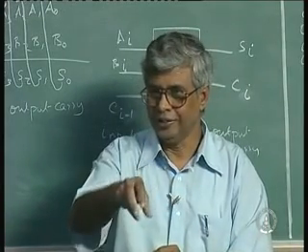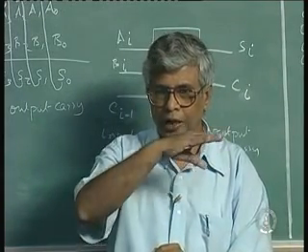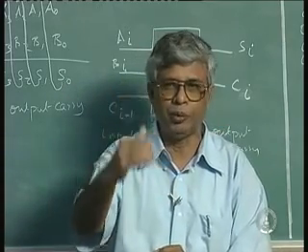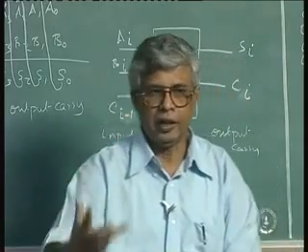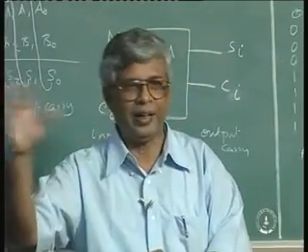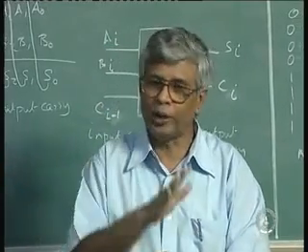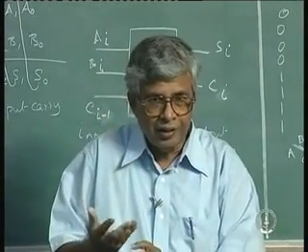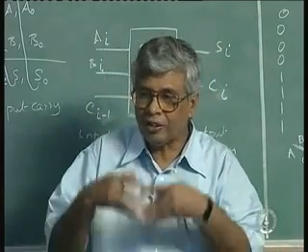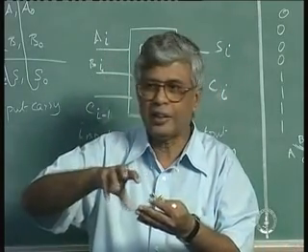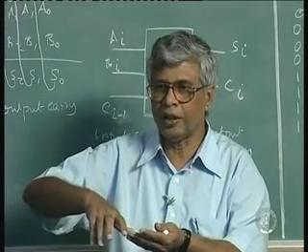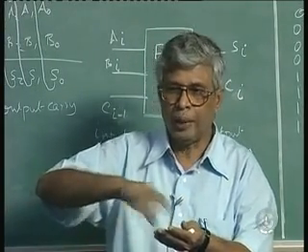I will use it. So after the minimum sum of product expression, all this corner mapping and minimum sum of product expression, trying to get as many ones as possible to be grouped together, all that is fine. I am not saying you should not do it, but after that also be a little bit vigilant. After that, some little manipulation can lead you to a very simple or elegant circuitry. That is what we did in the case of exclusive OR gate in use in parity check generator.